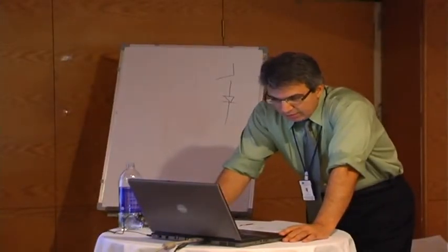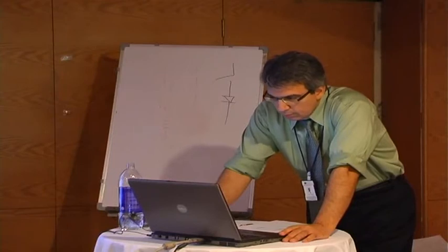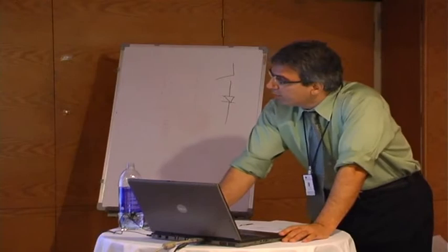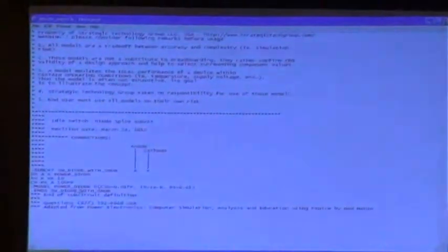So for the diode, we have a circuit file. This diode has certain parameters defined, and we also have a snubber included in this diode, which is a resistance of 10 ohms and a capacitance of 100 nanofarad.